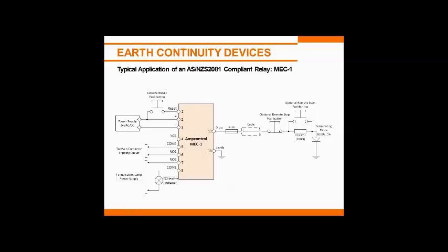And in this case, a diode's used for termination. A 1 amp diode. Normally we recommend probably a 3 amp diode there, but 1 amp will do in most cases. And a 1000 volt 1 amp diode is a fairly robust diode. The other inputs and outputs here are just outputs. The control output usually goes to a main contactor, and then there's some sort of lamp output as well to let you know that there's been a trip on the circuit.